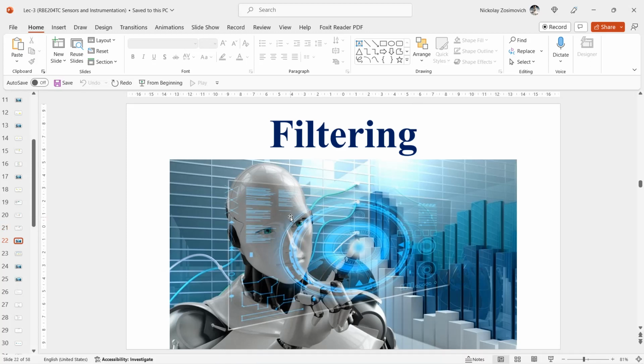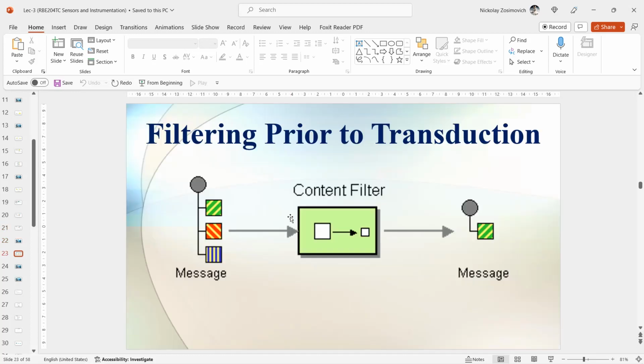Next subtopic, filter. Error signals can be reduced or avoided by filtering, to be performed either in the domain of the interfering signal prior to transduction or in the electrical domain after transduction. The unwanted signal may be kept outside the sensor system by several filtering techniques, depending on the type of signal. Sometimes the technique is referred to as shielding. We briefly review some causes and associated reductions.